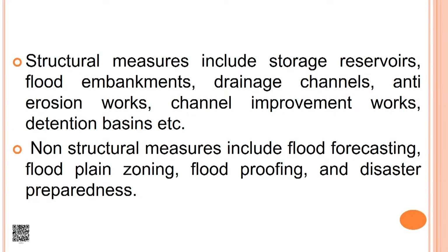Structural means include storage reservoirs, flood embankments, drainage channels, anti-erosion works, channel improvement works, detention basins. Non-structural measures include flood forecasting, floodplain zoning, flood proofing and disaster preparedness.